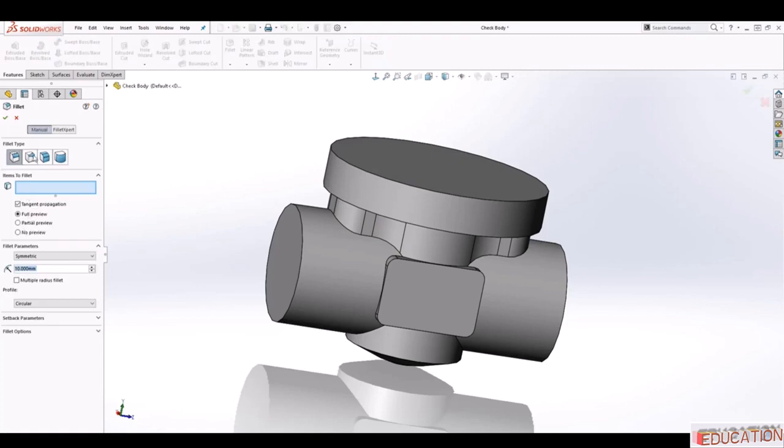So you have all these different types of fillet here. This is a variable size fillet. This is a face fillet, which is like you select two faces, and this is a round fillet, which, I mean, it doesn't apply in this part, but maybe I'll make another example where this applies. It makes a round fillet between this face and that face. But for this example, we are going to be using the constant size fillet, and you'll find that you will be using this fillet the majority of the time.